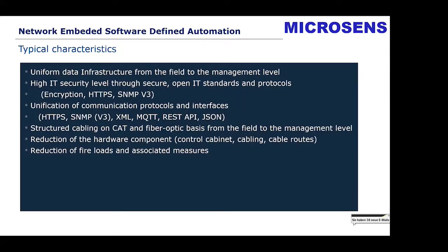On the other side, if you imagine that you have in the conventional way a lot of cabling between the device and the field, for example, this HVAC device to the cabinet, you have a big bunch of cabling in between. This is reduced because you have only the cabling on the device, the connection from the field components to the smart I/O controller, and the rest is connected only by an uplink.